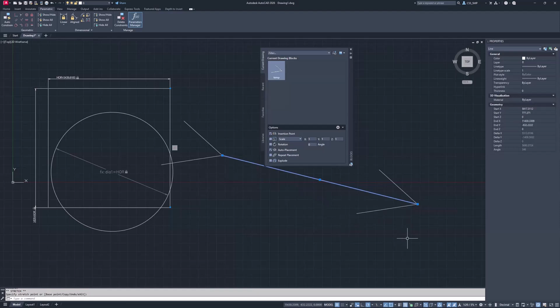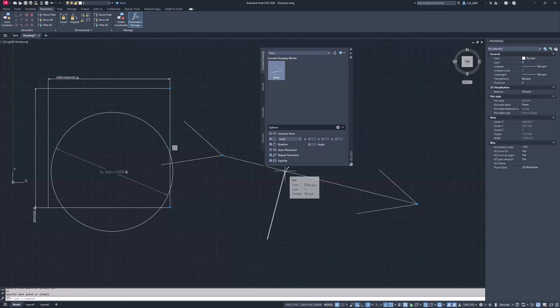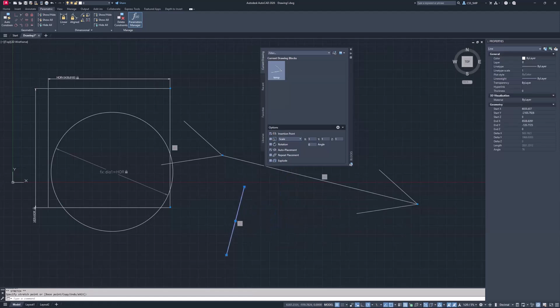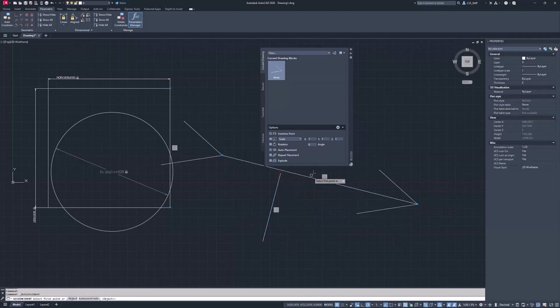Yeah, so if you had another line perpendicular to that, they're looking for the crossing over of those two lines. Okay, so if that's here, you would need to set a perpendicular. Right, and the perpendicular would hold that, to keep that perpendicular. And you probably might want a coincident as well. But it's only going to snap to the midpoint of that line. Yeah, okay. So there are limitations there.